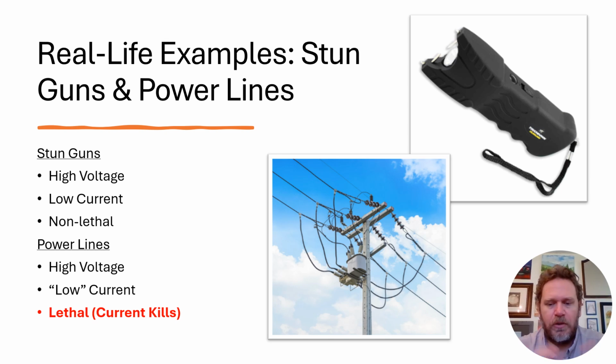I mean, huge voltages, huge electric potentials, but they're still non-lethal. And the reason they are is because these are what are called current-regulated devices. They have a very high voltage, but a very low and regulated amount of current available to them to move. We'll get into later how we can do this current regulation when we start talking more about power. But for now, just trust me, they have a lot of ability to move charge, but they don't have a lot of charge available. And the reason they want this is because current is what is deadly.